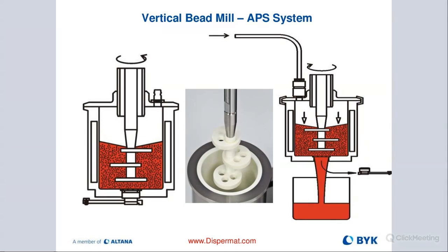That's a slide for the APS, what I explained earlier, that pot mill with the two-container system for the lab space. So with two containers, the top container has our mill base. We add beads, we mill. When we're done, we purge it with air. We hook up an air hose and purge it. And then the mill base gets drained or pushed out into the container on the bottom after we remove the drain plug. Again, different mill heads, ceramic. We also have ceramic-lined milling chambers for battery slurry development, which is critical so that we don't have any wear off our stainless steel into our slurry.